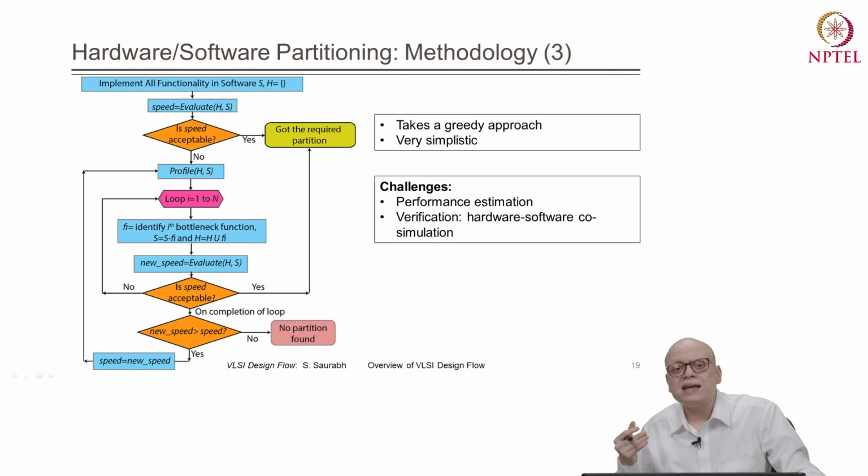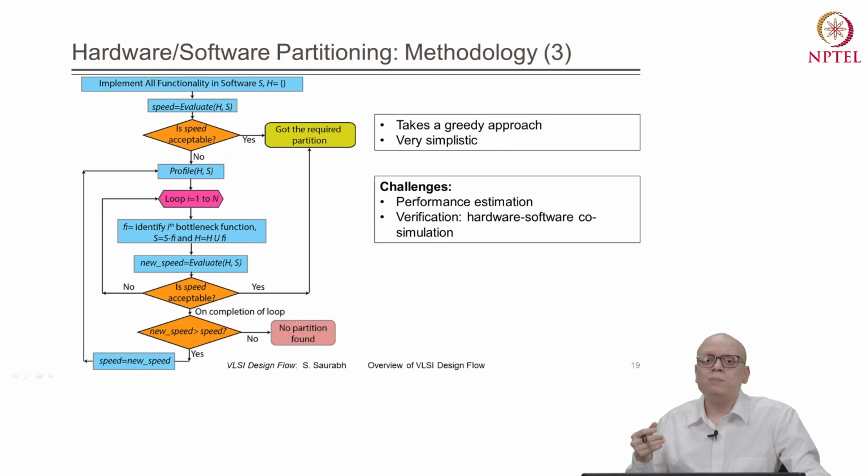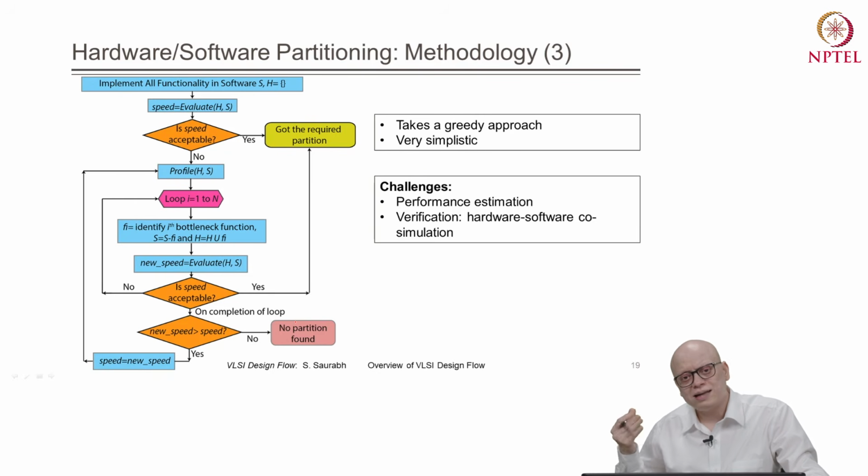Now how do we try to tackle this problem? We tackle this problem by implementing the hardware in, say, an FPGA, which can be designed very quickly because the hardware is already there, we need to program it. We assume that the function has moved to the FPGA, and based on that we can estimate how much gain we expect if the function is moved from software to hardware, right? Even for an ASIC we can extrapolate that number and check whether, if we implement that function in an ASIC, we will get a sufficient gain or not.